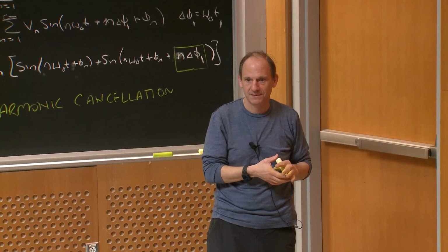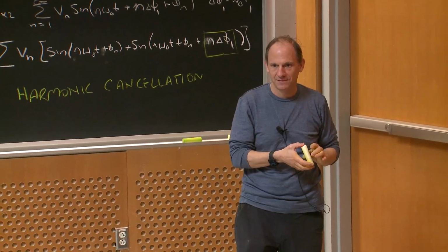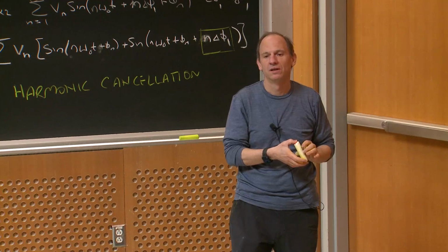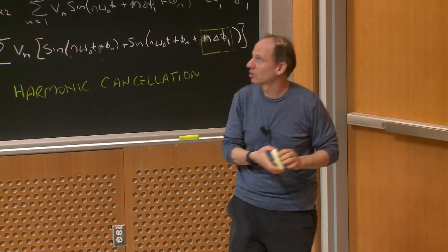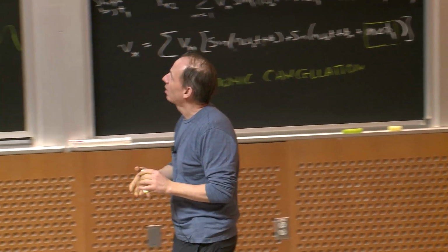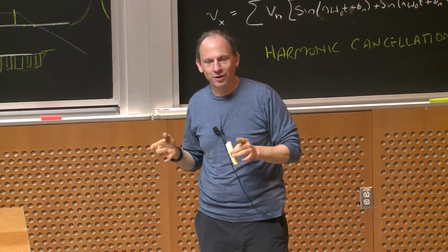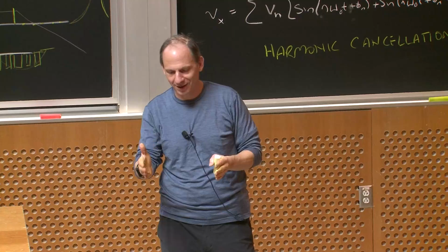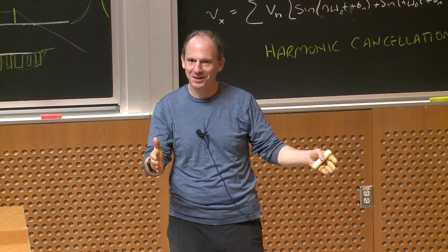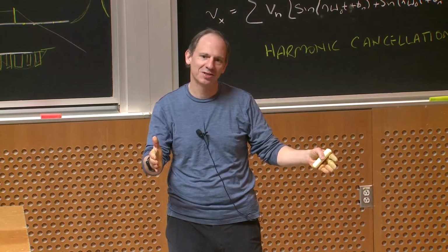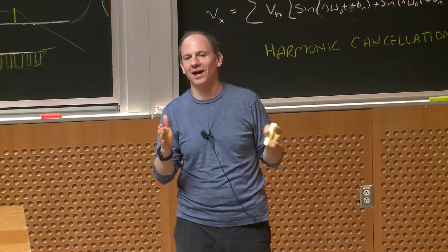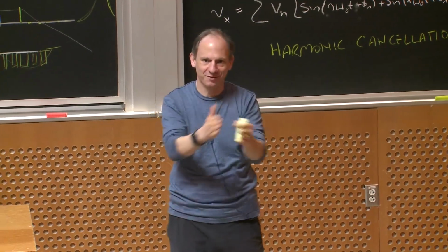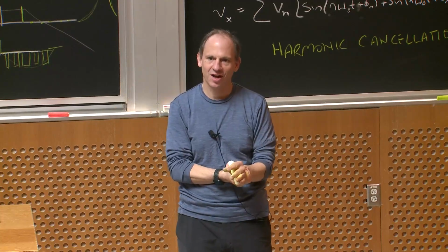Does the 6-degree displacement matter? Because it's a sine wave, but it's displaced by 6 degrees. Oh, yeah. Actually, if you look in the lecture notes, instead of displacing it by 36 degrees, I displace one by plus 18 and one by minus 18, and you get the same cancellation, and then it stays odd. So I don't have to have 0 plus a delayed. I can have minus half the delay and plus half the delay, and it still stays as an odd waveform.